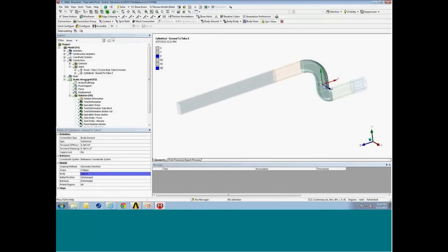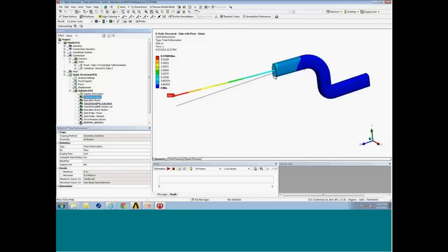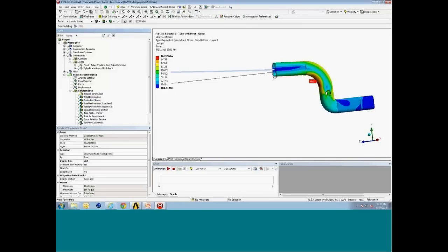When we apply the same loads and boundary conditions, we can review the results. We have lower deflection, but now we have some difference in the stress profile. So if we're interested in the details of this region, I'm going to go ahead and build a submodel of this region, including a much more refined mesh and all the features there. And that's what we have for our submodel.